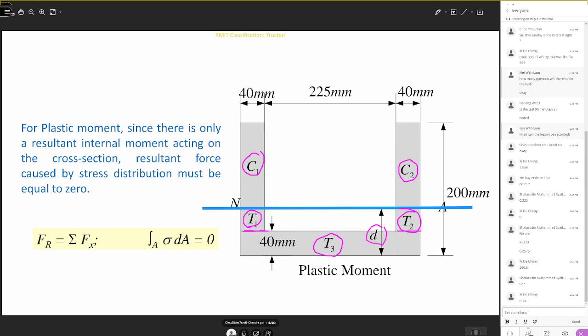So this is establishing the neutral axis on the cross section when the material undergoes fully plastic deformation. Okay, so we choose hypothetically some neutral axis. Above the neutral axis, we are choosing the zones of compression, so we call them C1 and C2. And below the neutral axis, we have the tensions. For calculation purposes, we call these zones C1, C2, and the zones of tension T1, T2, and T3.